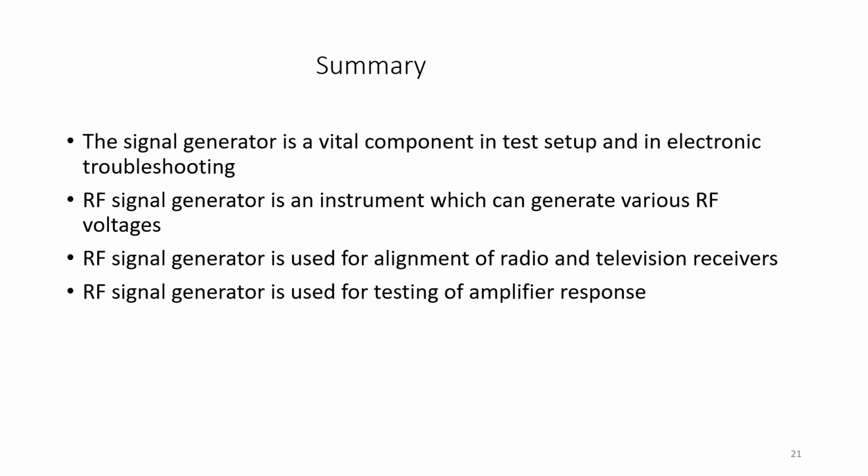The term oscillator is used to describe an instrument that provides only a sinusoidal output signal, and the term generator to describe an instrument that provides several output waveforms, including sine wave, square wave, triangular wave, and pulse trains, as well as they also generate the amplitude modulated waveforms, the frequency modulated waveforms to test radio receivers and the TV receivers.